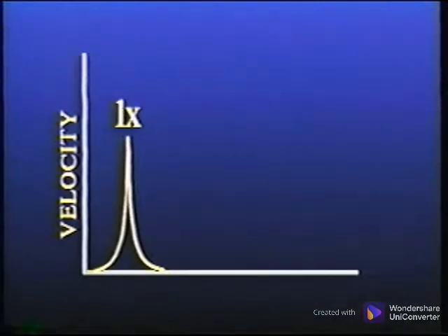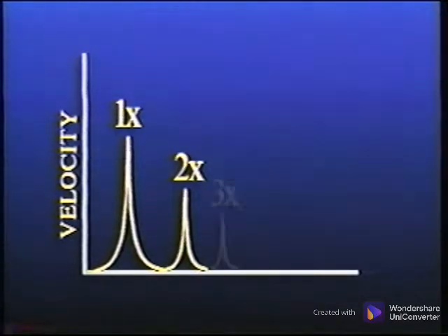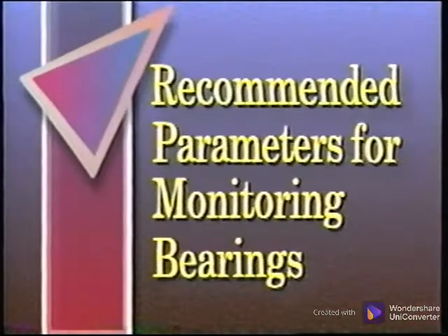To extend bearing life, it is imperative to pay attention to the peaks in the lower frequency range of the spectrum, which are commonly the root cause of the bearing degradation, such as misalignment or unbalance. Remember that our earlier discussion on viewing data pointed out the benefits of displaying spectral data in velocity, with the specific goal of seeing these low-frequency peaks as well as high frequencies. This spectrum has peaks that are indicative of bearing problems.